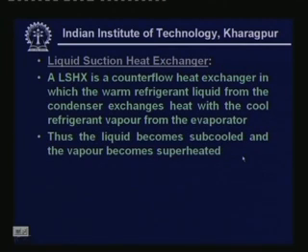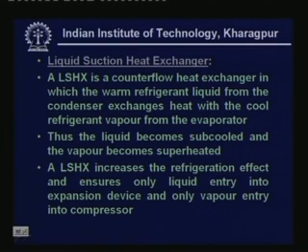So this is the summary of whatever I have discussed just now. Liquid suction heat exchanger is a counterflow heat exchanger in which the warm refrigerant liquid from the condenser exchanges heat with the cool refrigerant vapor from the evaporator. Thus the liquid becomes subcooled and the vapor becomes superheated. LSHX increases the refrigeration effect, as you have seen already, and ensures only liquid entry into expansion device and only vapor entry into compressor. So it has the double benefit of ensuring proper operation of expansion device as well as the compressor. So it is generally desirable.